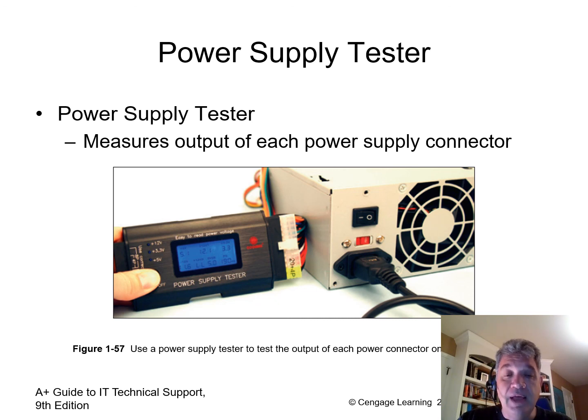But it's also worth noting that the power supply tester on the left of the screen here is plugged into a 20-pin plug that would otherwise plug into your motherboard, and that device is able to read the voltage on each one of the pins in that 20-pin connector. So it is very useful diagnostic information.